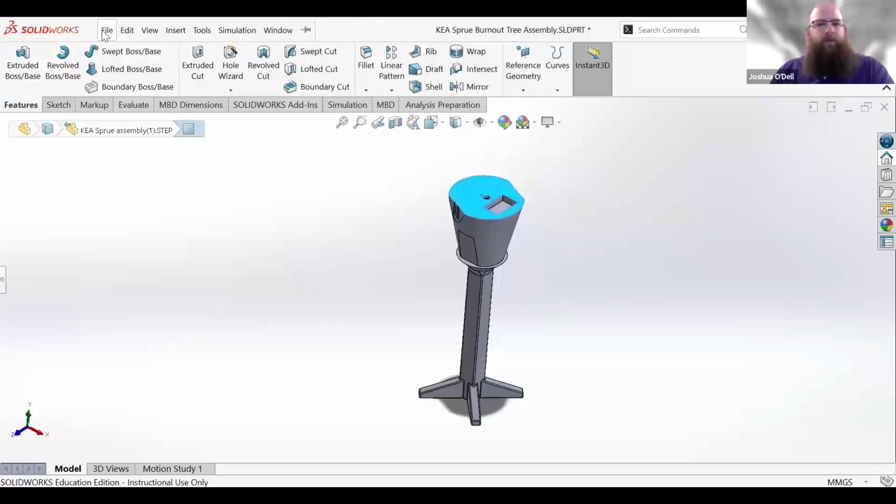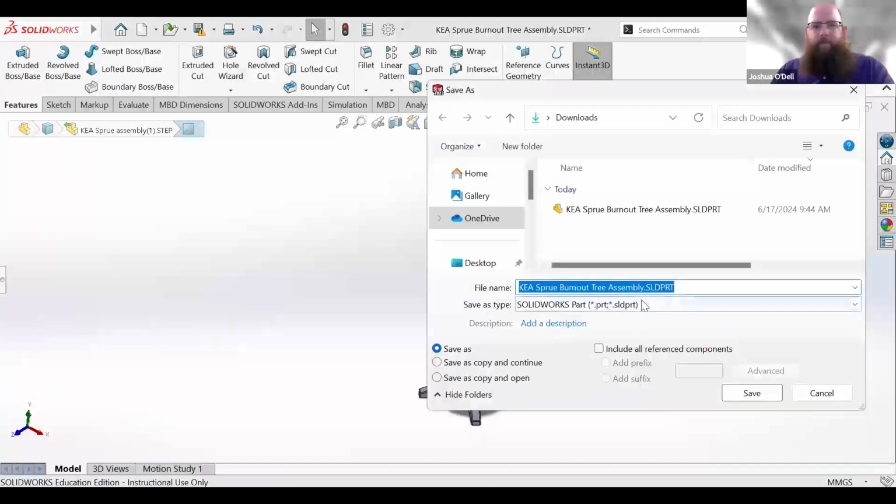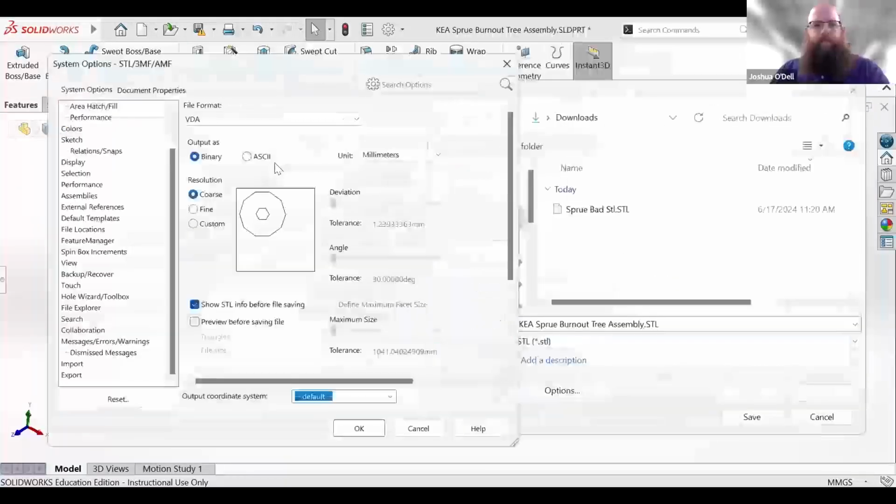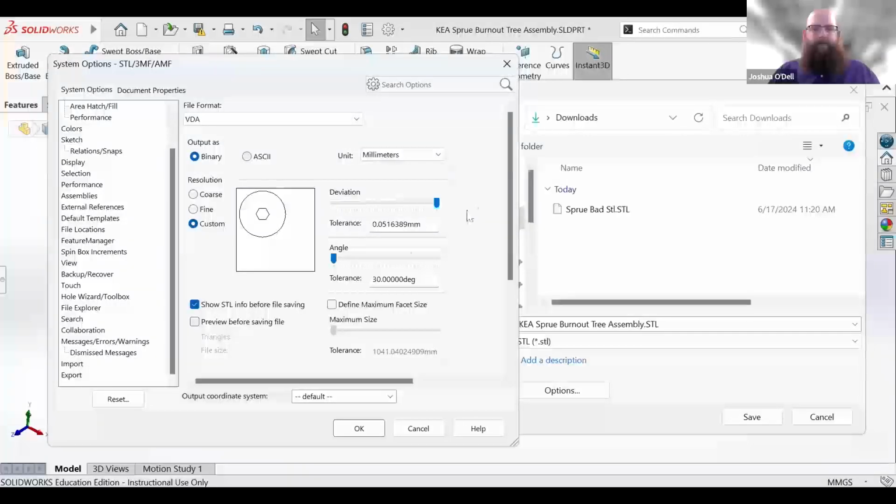And then we're going to save another one with the resolution turned all the way up. On the angle, for SolidWorks we usually stop at 5 degrees. You can increase the resolution of the angle even more, but there's some diminishing returns on how circular this is, and by increasing this even more, the STL file size will continue to grow and grow and grow. And on some patterns, it can grow too much, to where if you drop it in your slicing software, it'll crash the slicing software because of being too large a size. So we found this 5-degree angle for STLs actually works really well on SolidWorks.